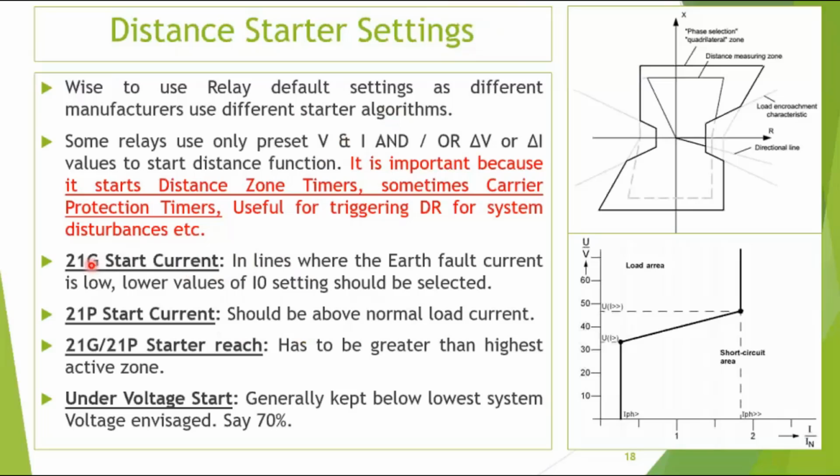The basic guidelines are that, but remember one thing, if there is a starter zone, the starter zone has to start before the zone will come into picture. So if we have some mistake, like in one case study I discussed in the earlier session, there the earth current of the starter zone was too high, and that is why the zone did not come. So it is important. It is not that it is a completely useless thing. It can come into picture if it is present.